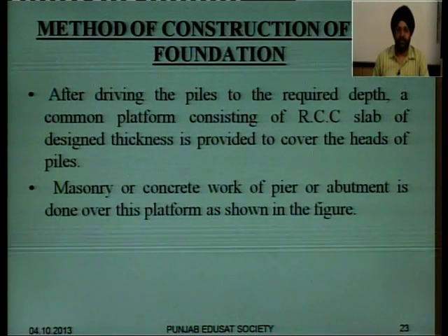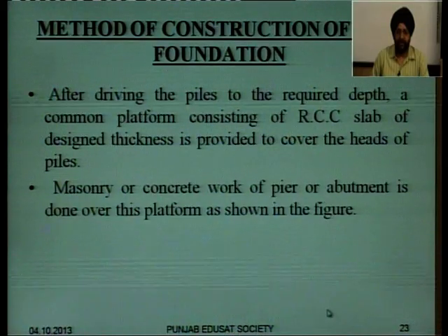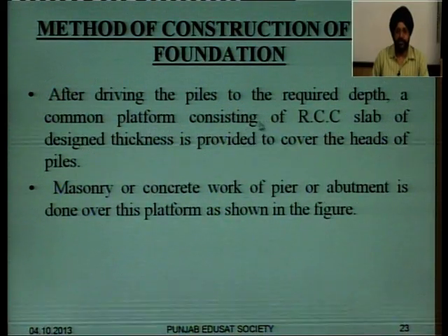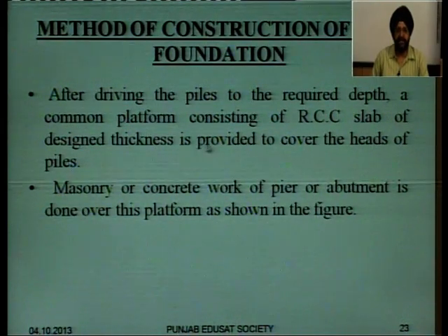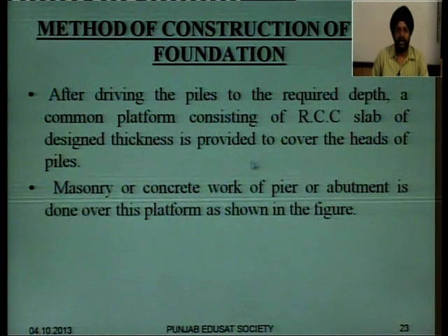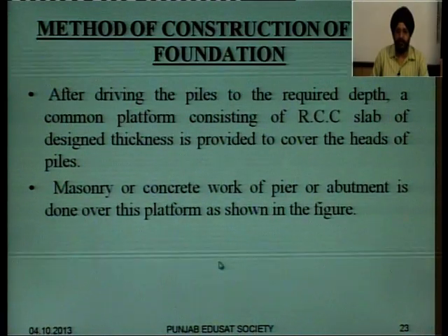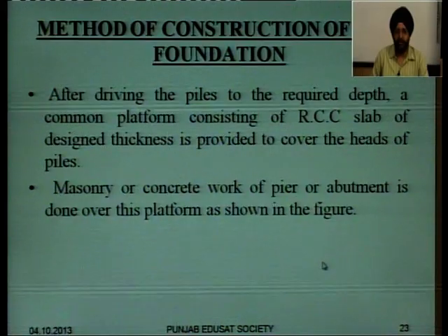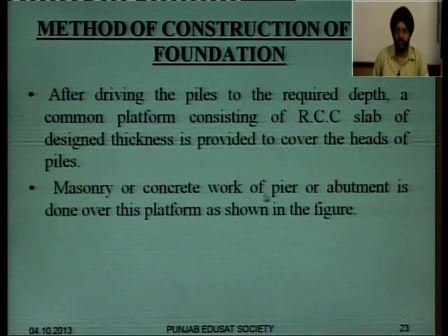After driving the piles to the required depth, when we get the hard strata, a common platform consisting of RCC slab of design thickness is provided to cover the heads of the piles. When we have provided a number of piles, we will cover the head of the piles by a common platform. As we have seen in the diagram also, we provide the common platform, and masonry or concrete work of the pier